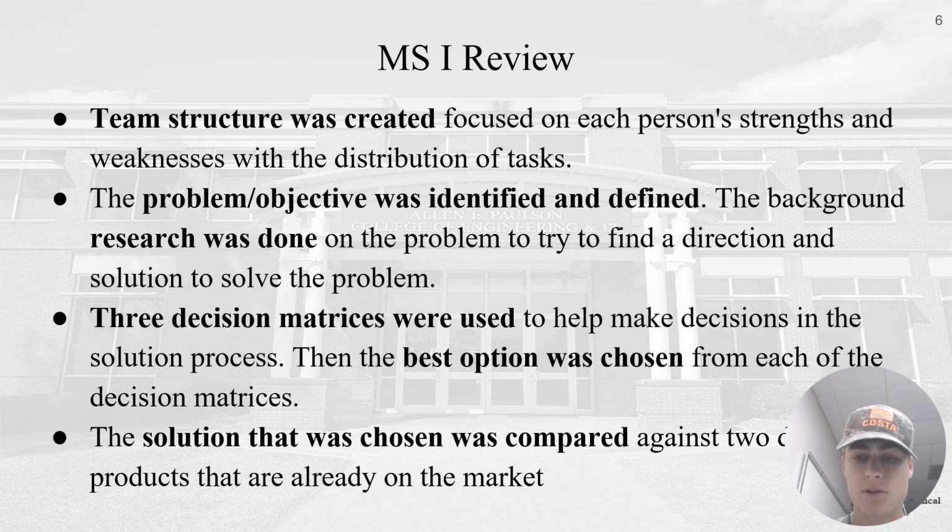And the background research: when we first were given this project, I did a lot of background research, and I was the one that originally found the Marionette software add-on and thought that was the one and only, as well as the best solution for using Blender as a controller for the servos, because Blender's naturally just an animation program. It's not designed to be a controller, but Marionette had some promising results on YouTube, and there was a GitHub link that ran through the whole process of using it.